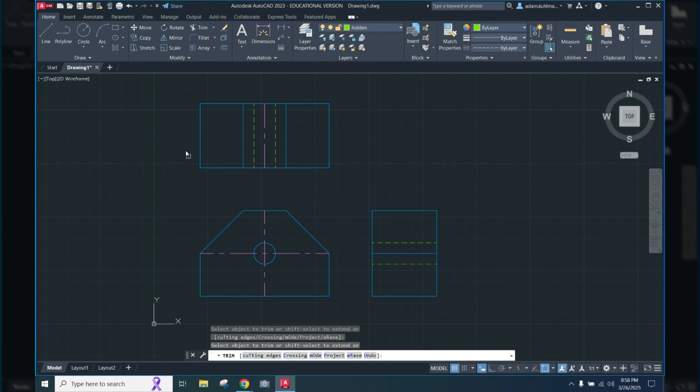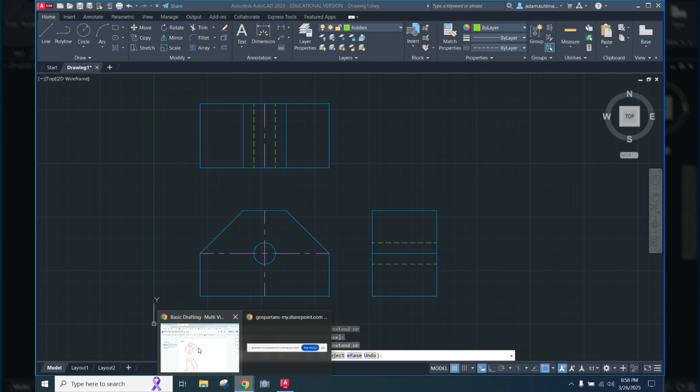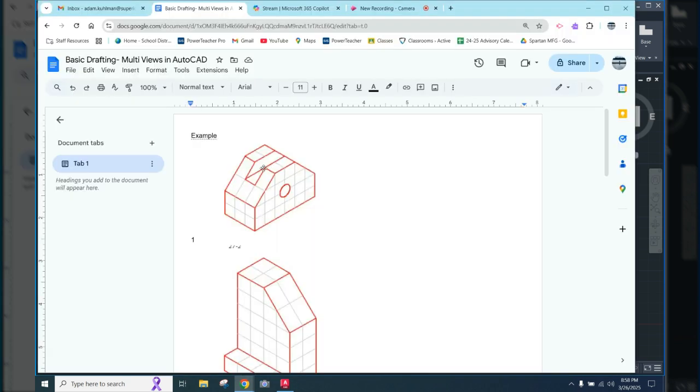Because there is a groove cut through this thing as well. We've got one more detail we need to add to this, which is this groove that's cut through. So in the front view, it's going to look like a hidden line. In the right side view and in the top view, we're actually going to see it as an object line. And counting the squares here, I can see this one is down 1 inch. It's in an inch from each edge, and if we're looking at it from the top view, it's in an inch from the two ends as well.